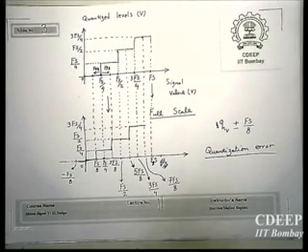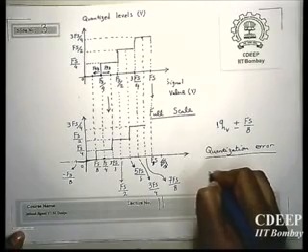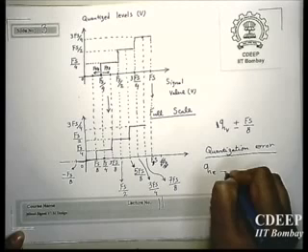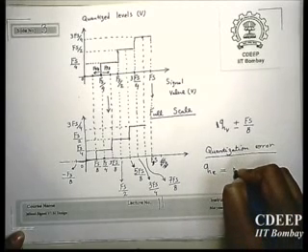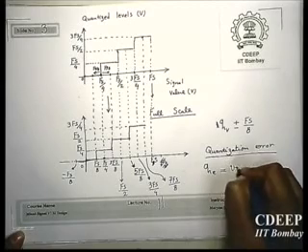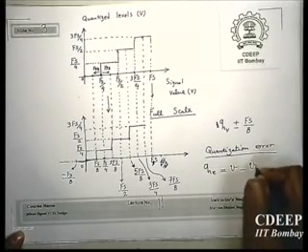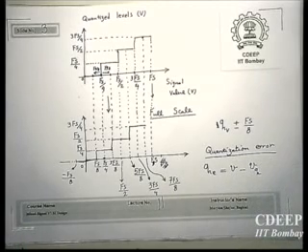So quantization error QE is equal to the signal level, the real signal V, minus VQ. V is the real value of the signal which is held on the capacitor or any storage element, ideally, and VQ is the new quantized value which is assigned to V. V is not V anymore; now it is known as VQ in this system.